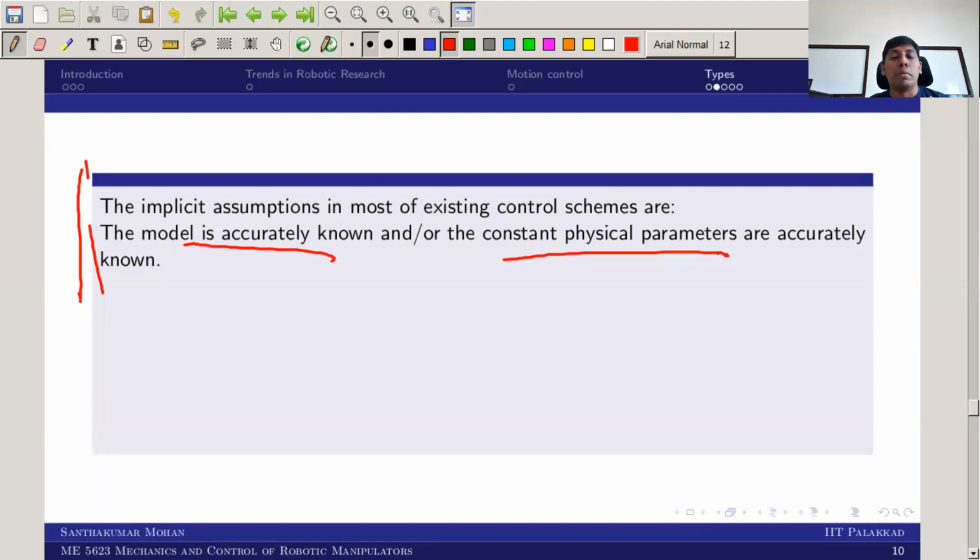Similarly, you think about it in control. Least affected, in the sense that your error variation is probably in the order of millimeters, but you are trying to correct even if it is at centimeter level. For example, the control input is supposed to be 10 Newton, but instead you are trying to correct with 100 Newton. You are being overwhelming. This overwhelming is one of the difficulties happening in robust control. That's why robust control, although popular in robotics, is not applied in real time, because it consumes lots of actuator energy.